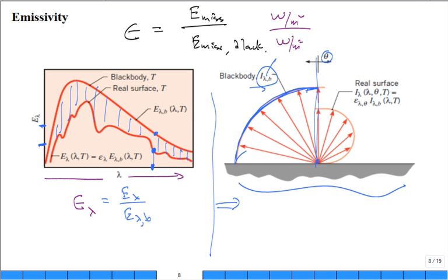And over here they're saying not just a black, but they're showing a real surface. What's the difference in the length of the line going from here out to there versus here out to there? That ratio is the emissivity. I wish they would have maybe started this arc and stayed on the same side. Because if they would have shown it like this, that ratio would have been the same ratio regardless of theta, wouldn't it?